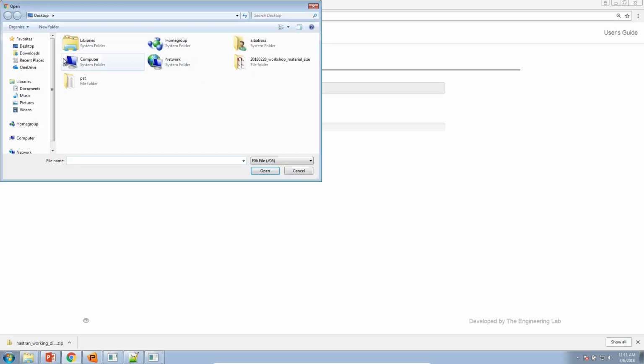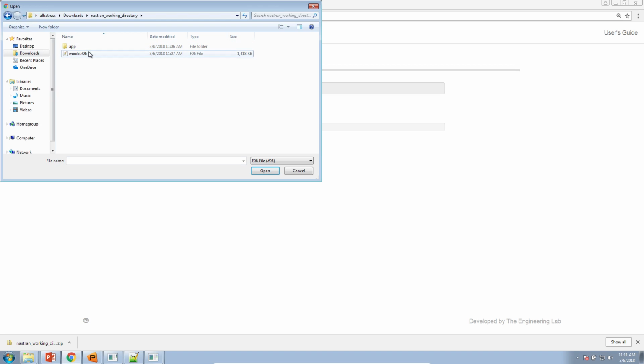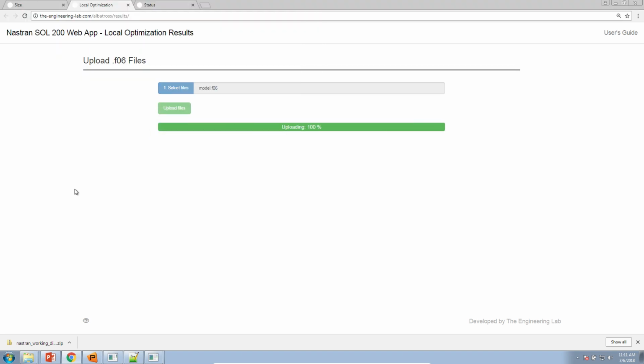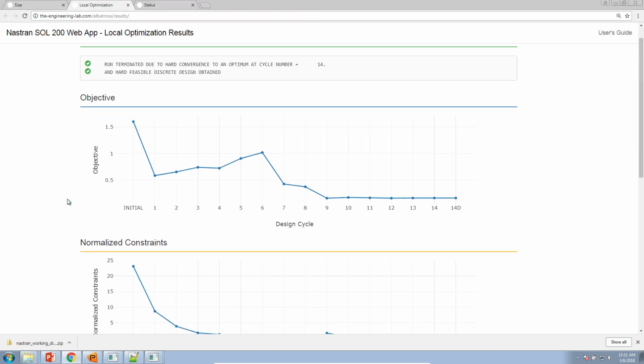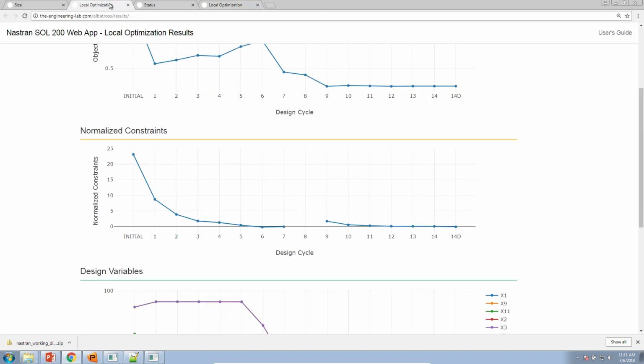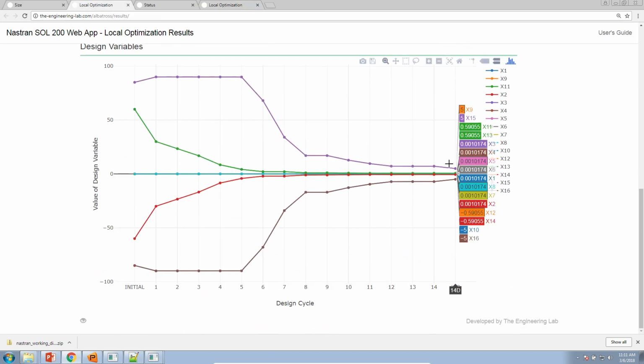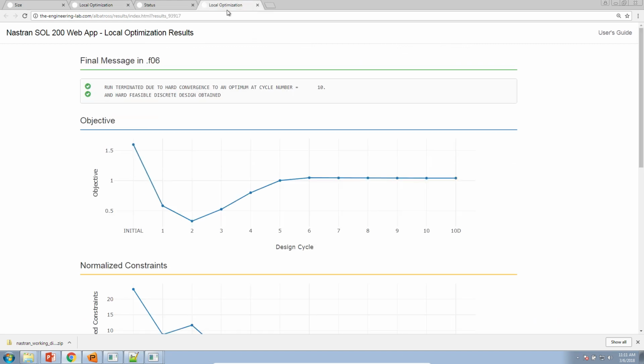For the original or the first optimization we performed, only the 85 degree plies landed on a ply that was in increments of 5. But the X11, X13, basically the 60 degree plies, landed on values of 0.59, which is not correct. I found my error. I performed the optimization. Here it's loaded the results for me.